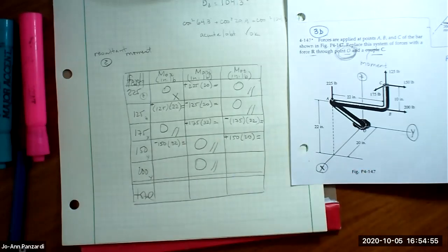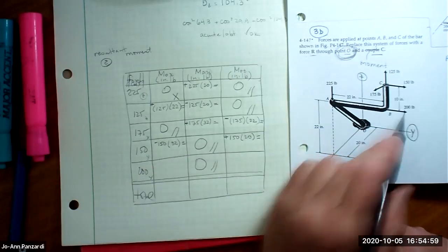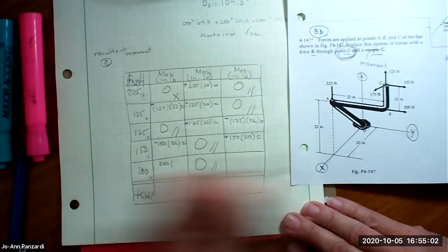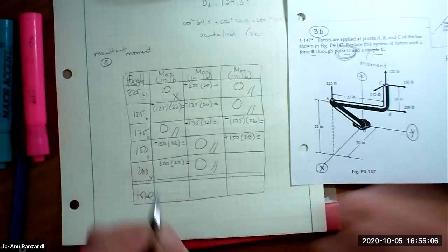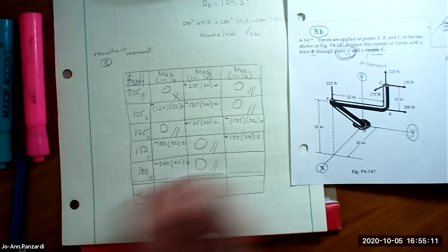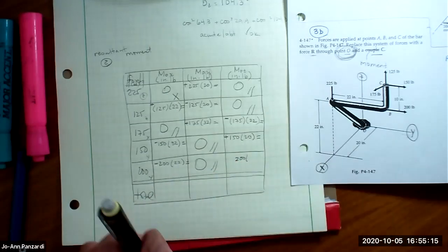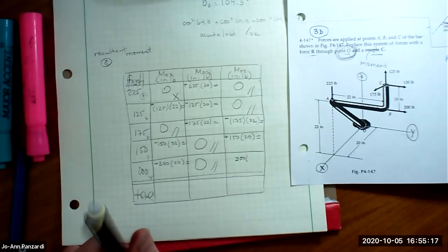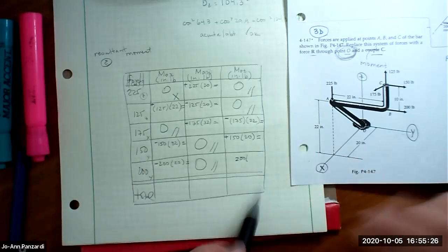Okay, we have the 200 left. So 200 is in the y. I want to find the moment about the x. So I have to use the z distance, 22. Fingers go in the direction of force. Palm goes towards x. It's a negative 200. This may be overwhelming, but the math's a lot easier than doing everything vectorially. In any event, this is what you're doing it by right-hand rule. You've got to get better and better at this.